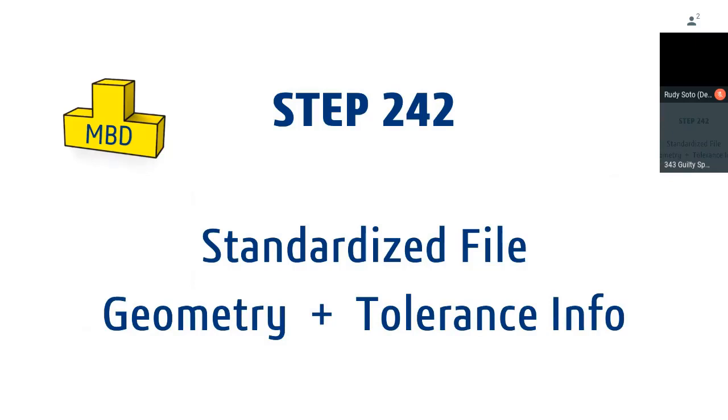So there's basically three forms of STEP now. This is the newest one. And the earlier ones, the difference between one and the other, we always get that call in tech support, was one of them would retain face colors and the other one didn't. So it was a pretty minor difference between those two, but this is a pretty significant difference.